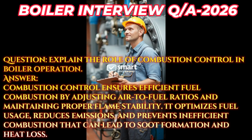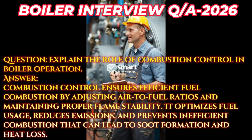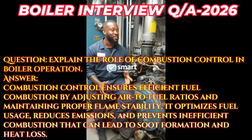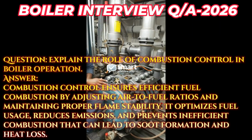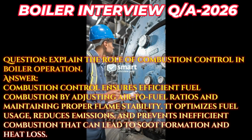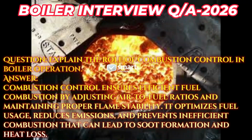Question: explain the role of combustion control in boiler operation. Answer: combustion control ensures efficient fuel combustion by adjusting air-to-fuel ratios and maintaining proper flame stability. It optimizes fuel usage, reduces emissions, and prevents inefficient combustion that can lead to soot formation and heat loss.